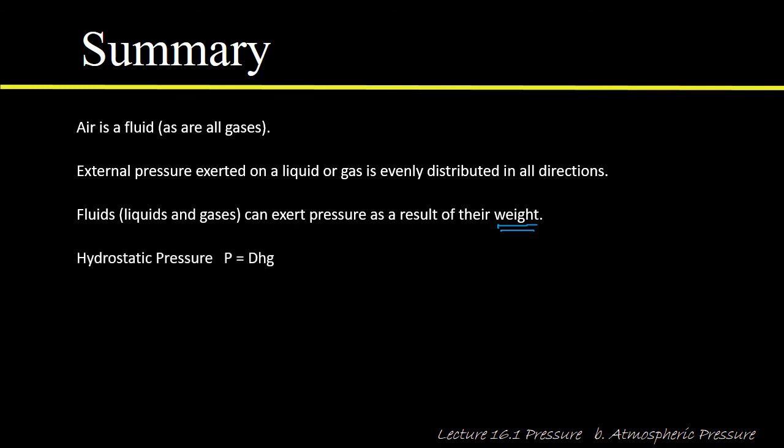For hydrostatic pressures, we've got this little equation. The pressure is equal to the density times the height, that's the distance to the surface of the fluid, times g. And remember that to use this, the density should be in kilograms per cubic meter. Okay.